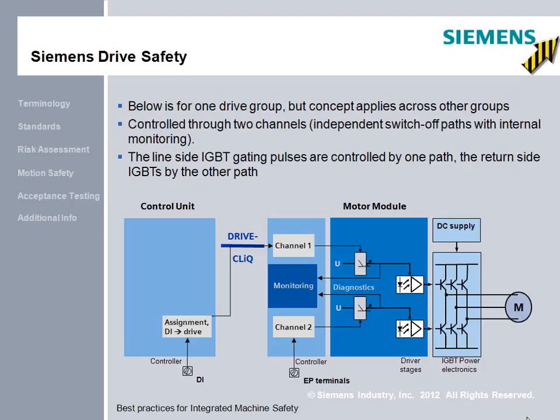If either of the channels does not fire its opto-isolator, that in essence will not fire the IGBT or power transistors, and the servo motor cannot move. So now we have the capability to functionally control this motor. Electrically, we're still connected to the power source, but functionally, the dual channel fail-safe redundant control system can stop the motor from commutating.